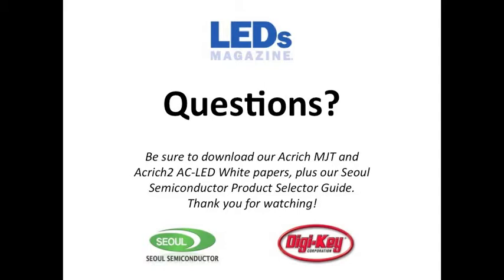It really depends on the type of LED in the package. We'll list typically a max junction temperature. On some of our modules we recommend a max case temperature for the board itself. Then you need to look really probably at LM80 and TM21 calculations with your operating temperature to understand what the lumen maintenance of that device is and if it fits your needs.